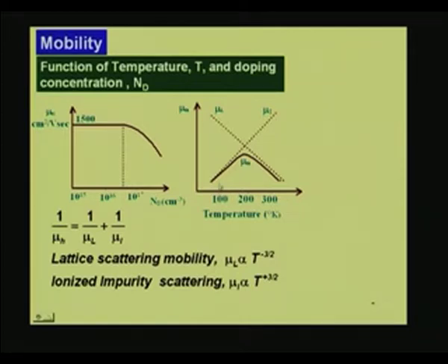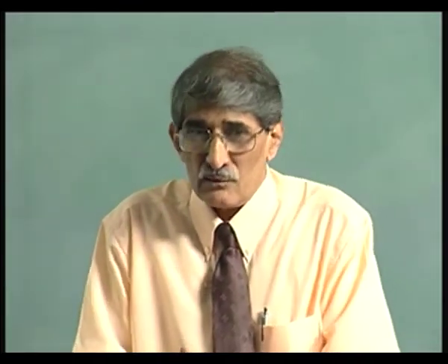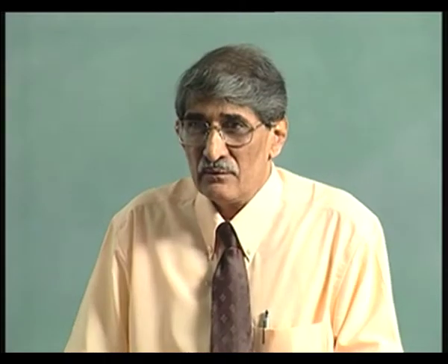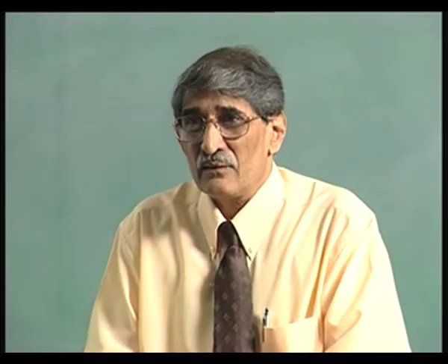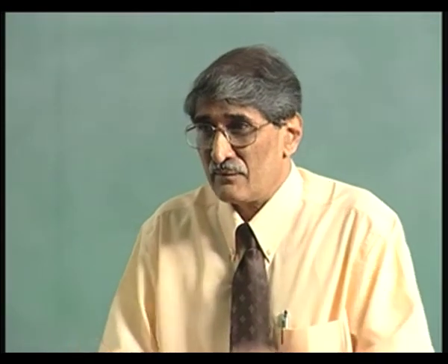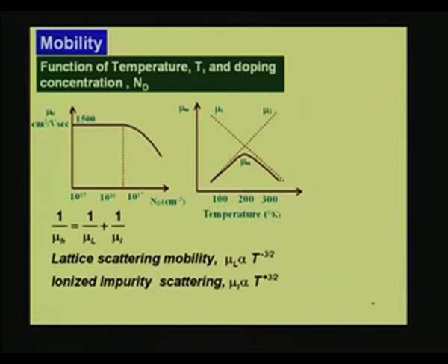Later on we will see, when you go to high electron mobility transistors with gallium arsenide, those devices depend upon this property. In the sense, the ionized impurities and electrons are not in contact with each other. There are two regions which are created which separate them out. Still, there are enough electrons, but the dopants which supply those electrons are kept in some other region. They are isolated from each other. So, that way you can make use of this. In fact, that is what we want to discuss later on when we come to gallium arsenide devices.